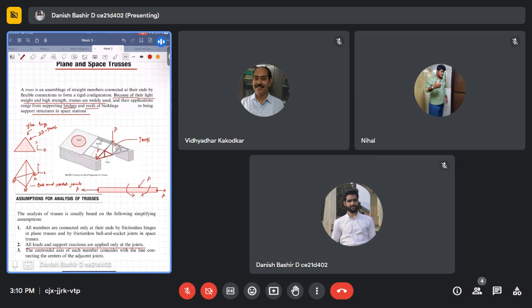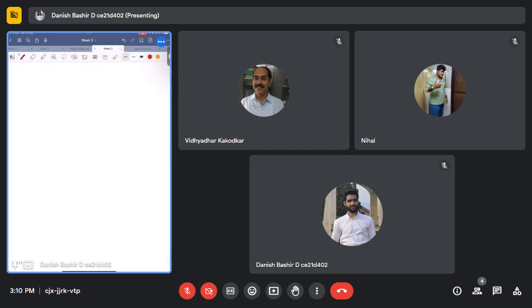Another, third important assumption is that the centroidal axis of each member coincides with the line connecting the centers of adjacent joints. For example, I have two members like this. I have one member like this, another member like this.